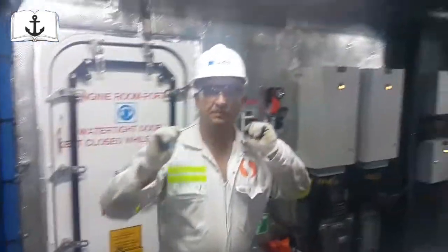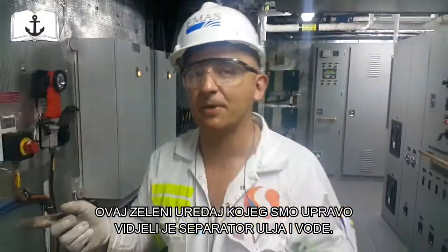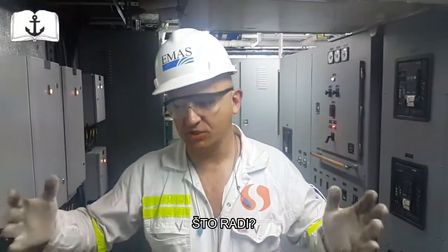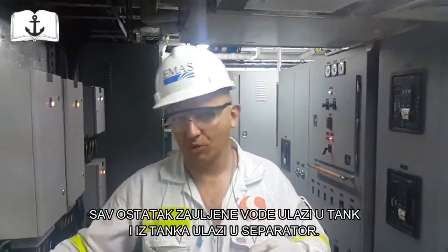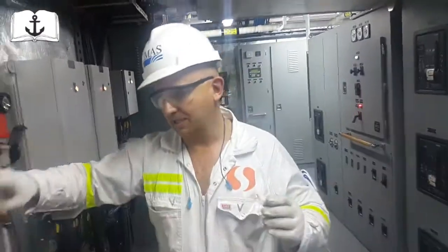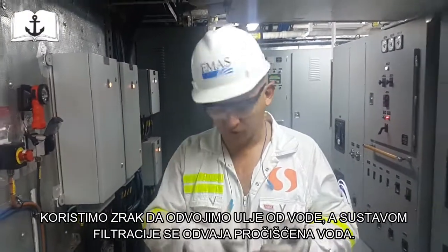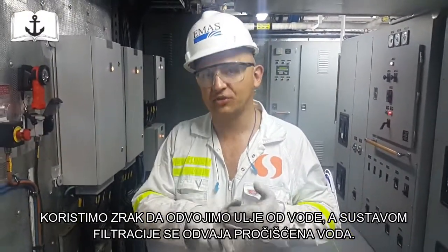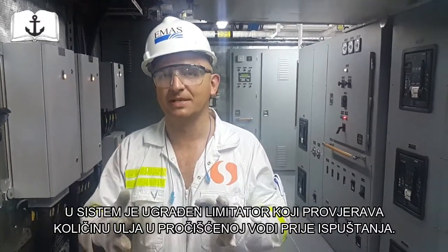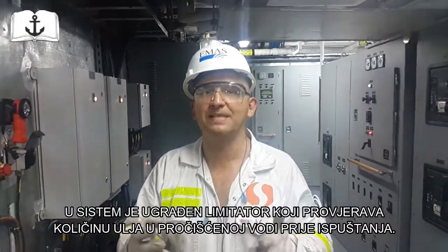So we just saw this green box or green unit. It's the oily water separator. What does it do? All the residues of the oily water or bilge water are going to the tank, and then the guy is coming here, starting up this oily water separator, and you're using a mixture of air and water, and there is a filtration system to discharge within the proper limit. There is 5 ppm or 15 ppm, depends on the zones.